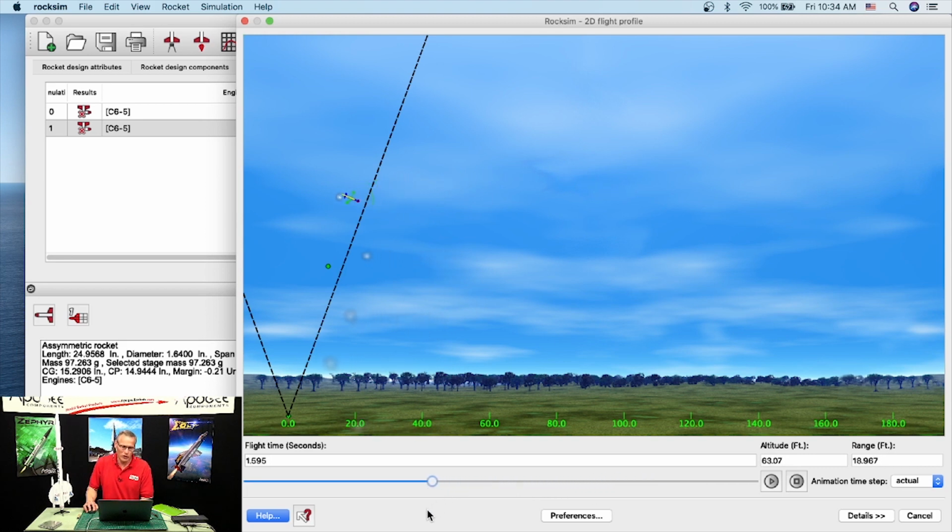This is why we always want to make sure that when we launch, that static stability is stable. So here we're coming off launch, we're cartwheeling over and over, and all of a sudden at this point, it's getting stable and more stable and more stable, and now the motor actually burned out. But just imagine if that was a long burn motor. It could cause some damage. So that's what we want to avoid. And again, our apogee point is way outside the weather cocking cone.